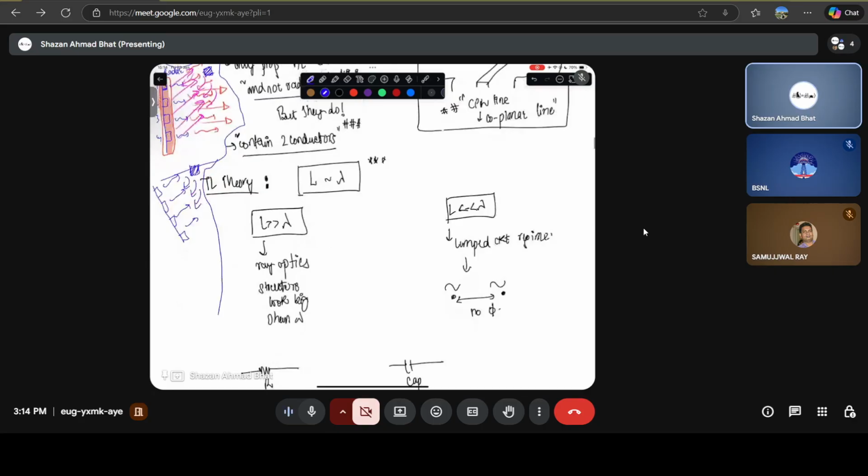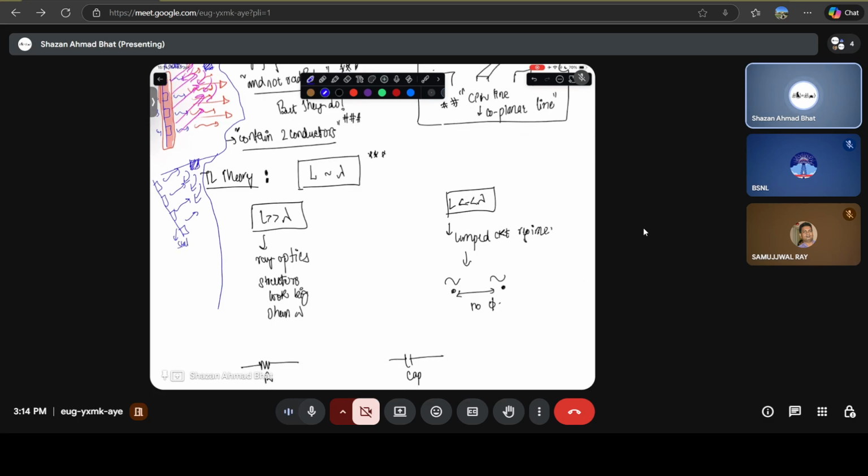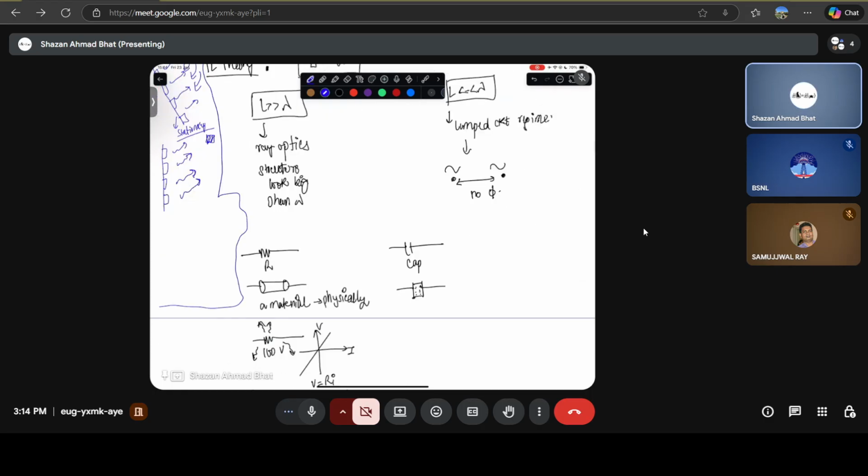This is one way. This is the old way. You are not every time going to turn the radar, or you are not every time going to move the big thing altogether. Or in certain applications, you are not going to move the antenna itself. What you want is for this antenna to be stationary, but you want the electromagnetic waves to go in the other direction. That means you want the antenna to be like this, but the electromagnetic waves should go like this, so that it can hit the object here. How are you going to do it? That is basically the trick behind phased arrays and where these phases are used.